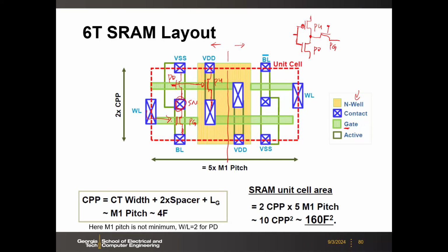So then the question here is, if we really want to have this F square stuff, then how many F square? It's not a good definition, but let's still assume F is the same as the tech node. We discussed what is really scaling, but from the normalization point of view, let's have F the same as the tech node. It's just a way to normalize the area into F square, the unit area.